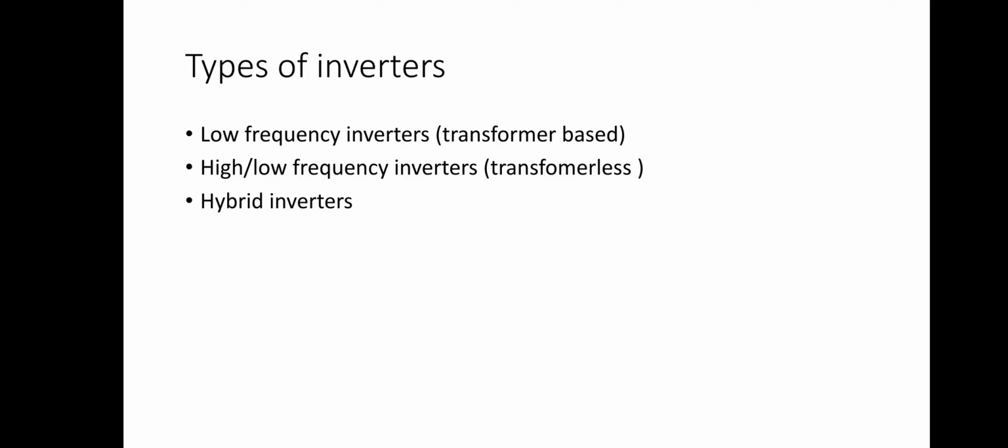So this kind of inverter uses 50 or 60 hertz frequency. That is for the low frequency inverters. Most of them are transformer based inverters. So they use a 50 or 60 hertz frequency switching speed to generate their output.